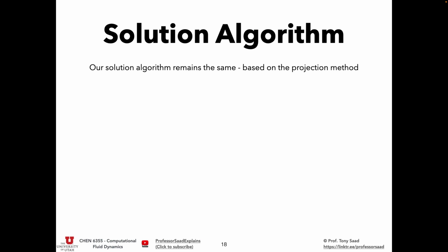Well, guess what? It's no different than last time. It remains the same. We can write these equations first. Assume we do advection diffusion only without pressure, and we will call this u tilde. You will notice that I will use this u tilde more in the finite volume discretization, because I need that temporary variable to store things in it. So I will use this nomenclature moving on: u tilde, an intermediate velocity field that's not mass conserving and that doesn't have a pressure.